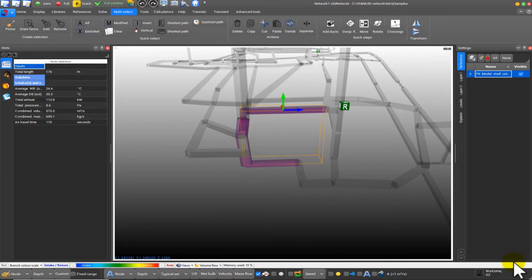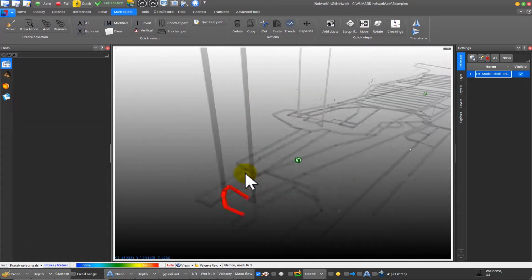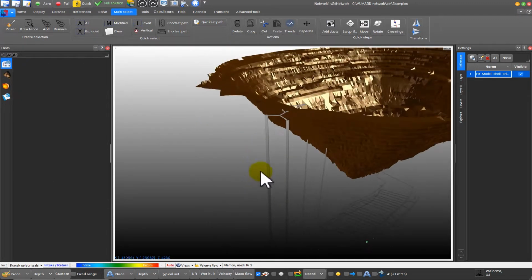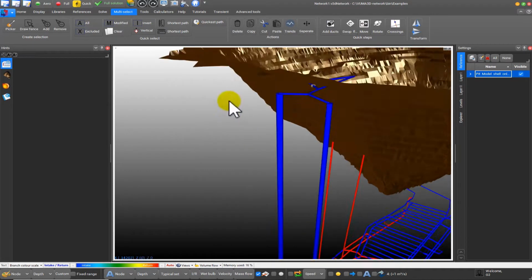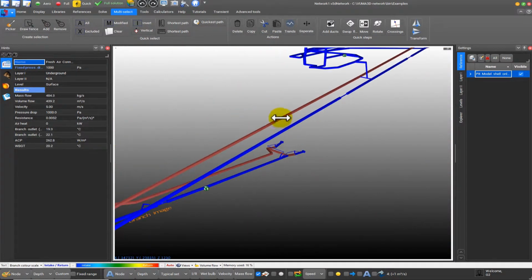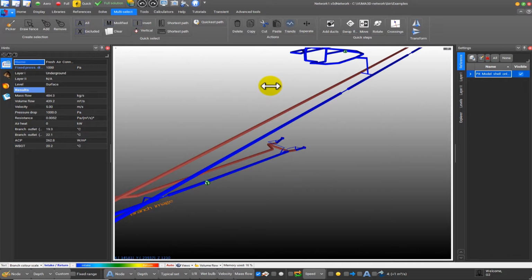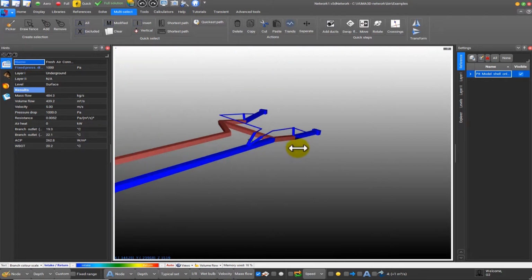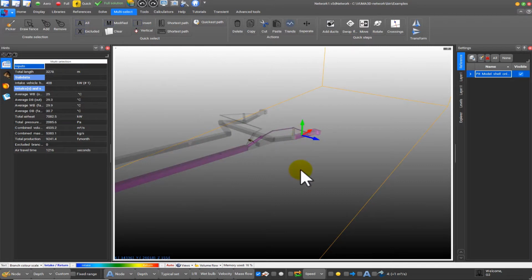The third path tool that we have is the quickest path tool. This one becomes more relevant when you want to check, for instance, the time stench gas will reach certain parts of your mine. Normally stench gas will be released up on surface. So we'll pick our deployment point, let's say over here. We want to see how long it will take from the bottom or from the top of the downcast shaft to reach our development end over here.